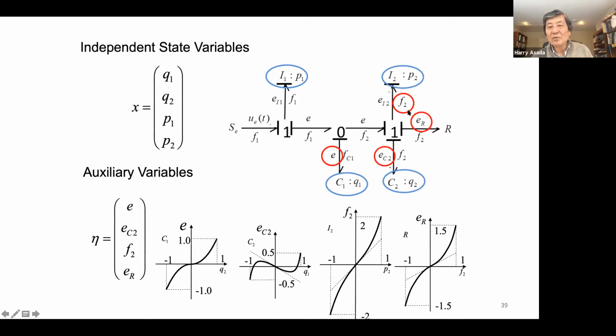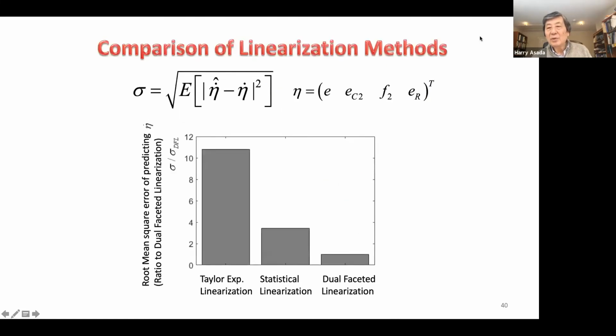Okay, and then we identified all nonlinear elements and identified the outputs from these elements. These are the auxiliary variables, observables, right? We put them together: original state variables plus auxiliary variables. We have 4 elements, 4 auxiliary variables reflecting 4 nonlinear elements involved in the system. We went through this analysis, and it turns out that the prediction of the first equation, dx/dt, is the exact equation, so don't worry. The problem comes from the second state equation, d eta/dt, and prediction accuracy is a very important part, right?